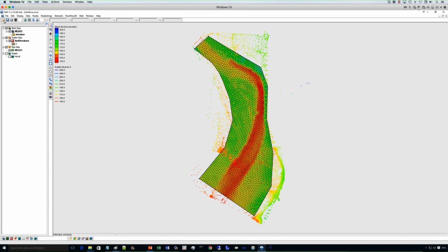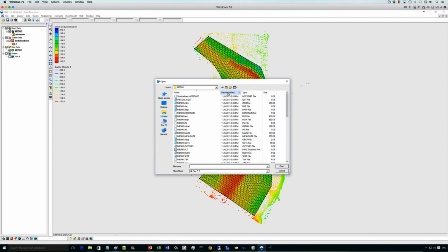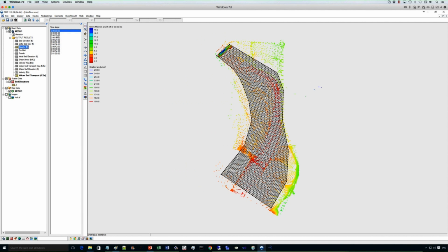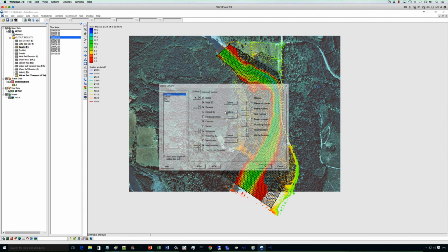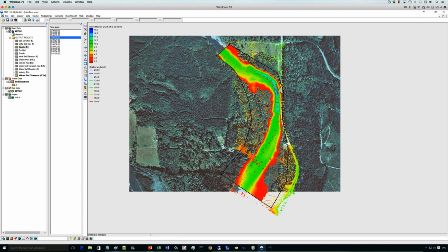When you close the model, it writes other results, and you can also import the results back here for post-processing. So if you import the results of the run you just created, you can use this file here, and you can see, for example, the bed, the depth. You can turn off the elements if they become annoying for your view, or you have a number of things you can do here. For example, removing the elements. You can turn off the scatter set.